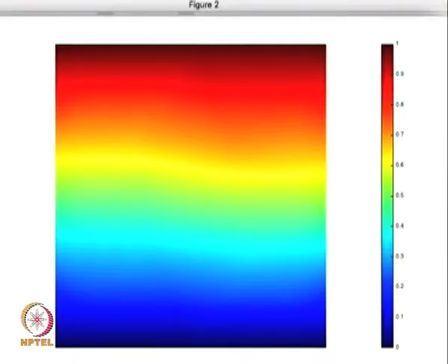This can be improved if we go into a very fine discretization and get a better result based on that. So let's now go back to the code and reduce the discretization a bit so as to generate smaller tetrahedrals so that our accuracy can be improved. The way to do that is, in the code we have to set the value for h, which is a parameter that we are going to reduce. So let's go back to the code.